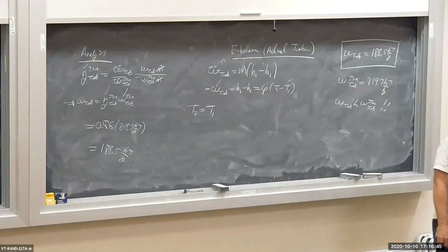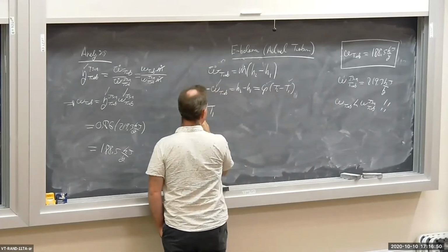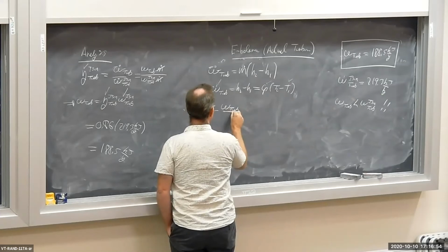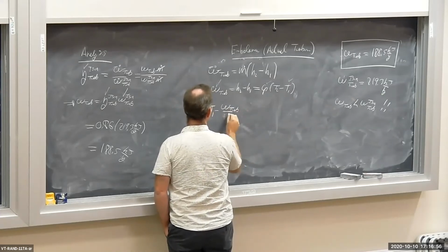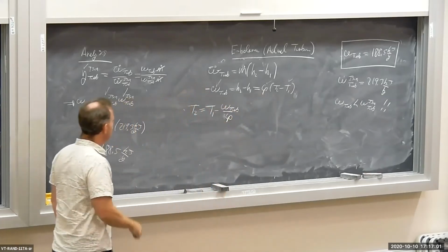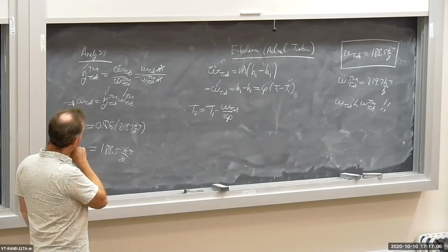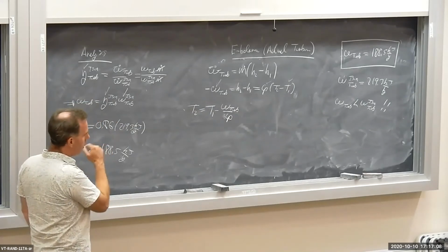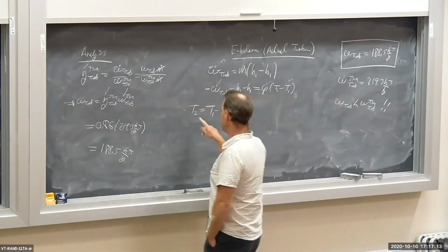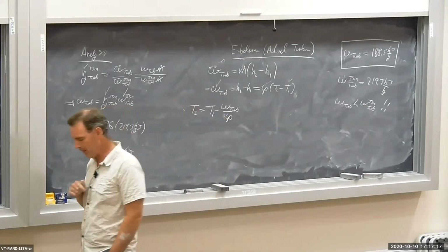Forgot the negative sign from the first law. Sorry about that. So I get T2 is equal to T1 minus W turbine over CP. Divide both sides by CP, take the T1 over on the left-hand side of the equation and flip the equation. And I get T2 is equal to T1 minus W dot turbine over CP. Okay?